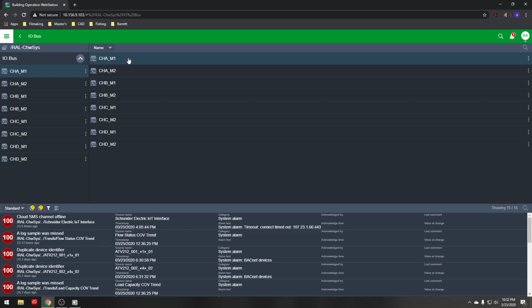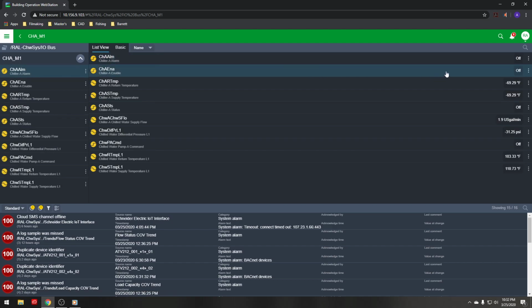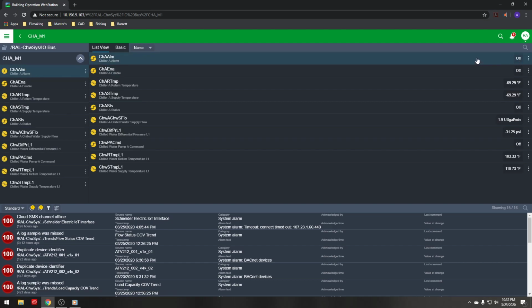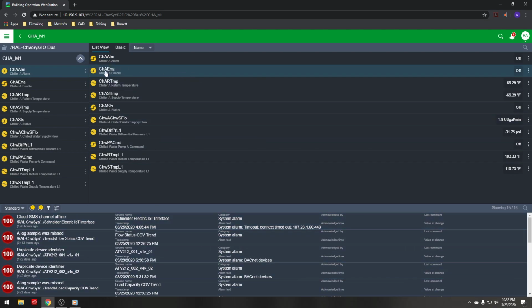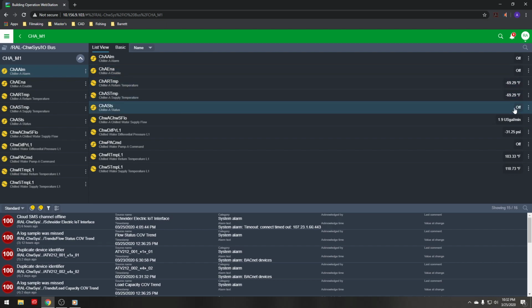So jumping in, we'll just get right into it. Here we can see if the chiller is in alarm. We're getting hardware points from that saying if the chiller is in alarm, this will be on, and you'll also get emails. It will show up here. Whether the chiller is enabled or not, we're in hand right now. We're in a very much a manual mode, so that's always going to be off. There's no sensors hooked up to this, so you're not getting that.